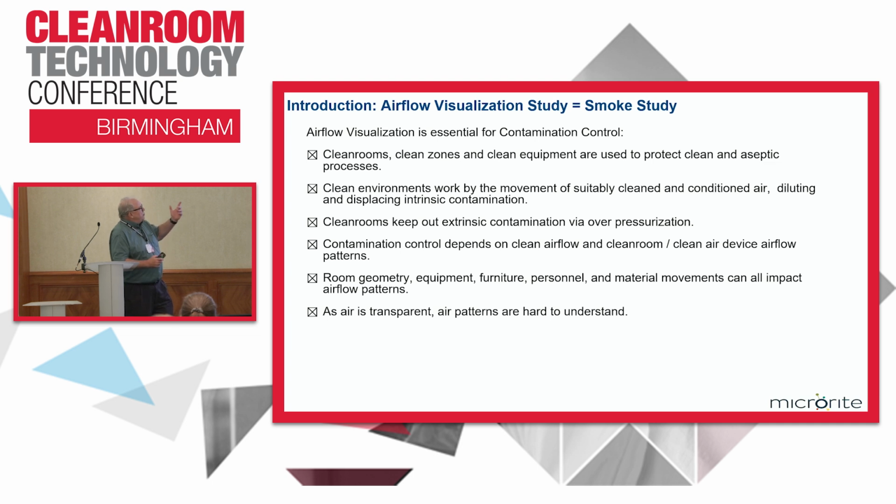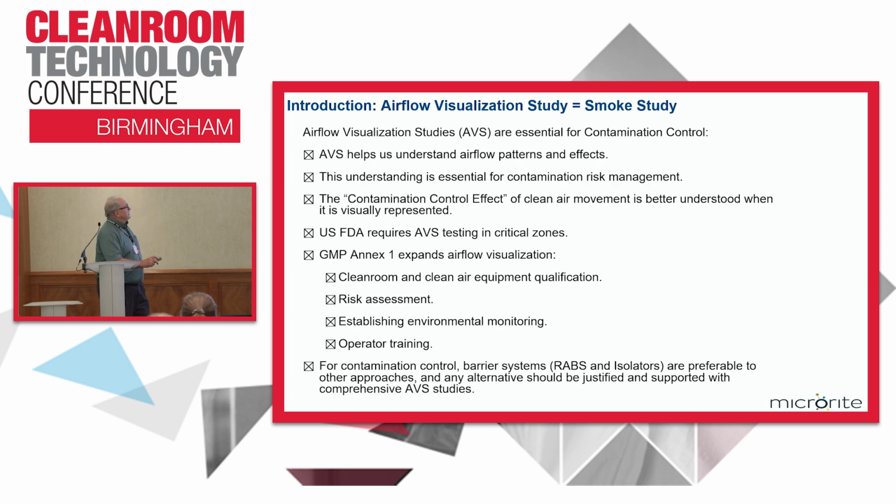Room geometry, equipment, furniture, personnel, and material movements can all impact airflow patterns, and because air is transparent, it's hard to understand. Airflow visualization studies help us understand airflow patterns. This understanding is essential for contamination control and risk management.